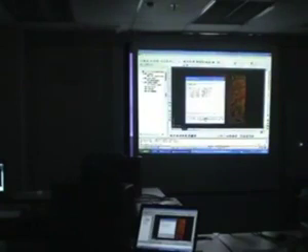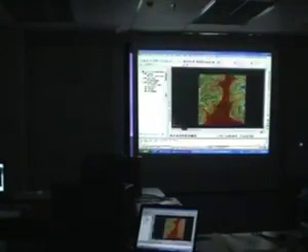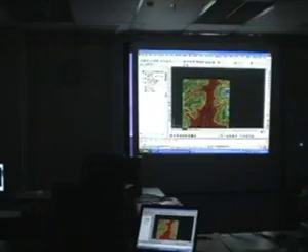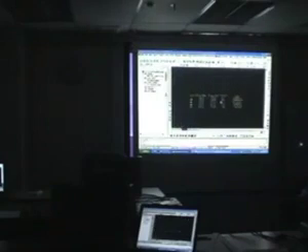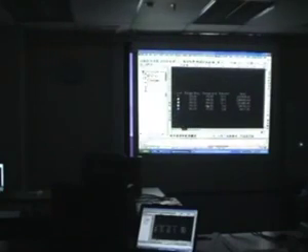You can even put a legend if you like. I'm just going to click legend, so OK. You can see how the colors are really being shown. So red color indicates the lowest elevation, if you remember, then followed by yellow, green, cyan. So the legend, I'm just going to insert it here. When you zoom in, you can see, okay, this is the legend which you can use. The color is red, this is the range, the percentage of the area, and also the total area in square meters.